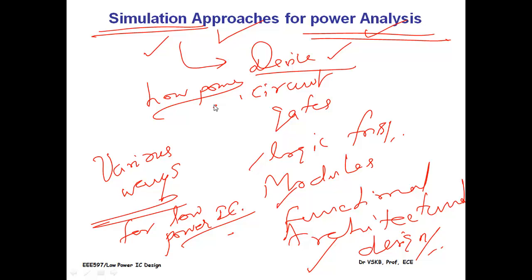And through these simulation based approaches, I go for making use of the EDA tools you had been using. For example, the Cadence tool what you are using, and the Xilinx tool, Altera, all these, they have modeled the circuits inside, and the use of such idea is enabling us to go for analyzing the power what we have out of the circuit while operating under such conditions, maybe even the temperature parameter, or the worst case best case models. That is what you have studied already, which help you to go for working with various process corner models for your applications. When you go to really work in the field, your circuit should be able to withstand everything, and all these are made possible through the simulation approaches so nicely.